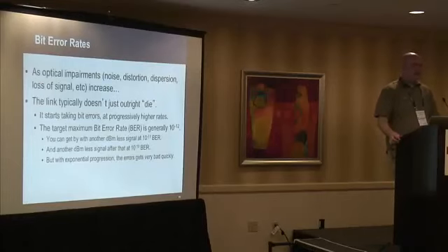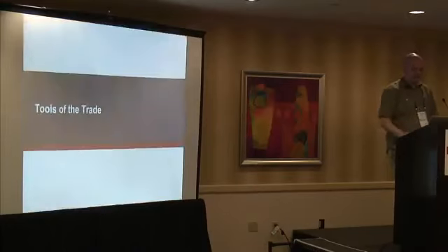Typically, you try to target a bit error rate better than 10 to the minus 12. But as you get down to the end, literally 1 dB of loss will cause a 10-fold increase in errors. Then all of a sudden, you end up with a very, very errored link. If it's right on the edge, you might not even notice it at first, and then someone bends a cable, and all of a sudden it goes over the edge.